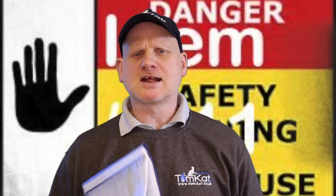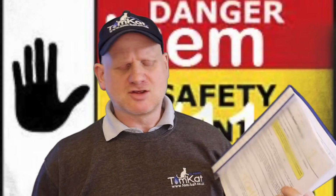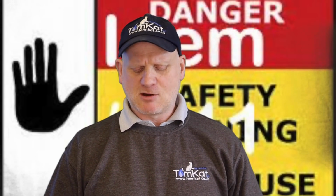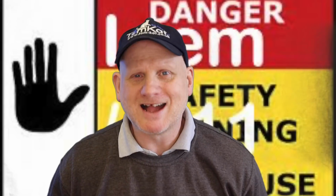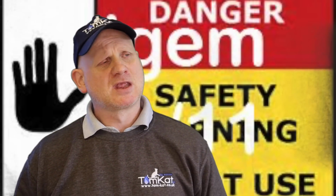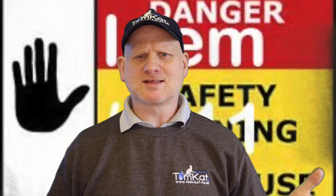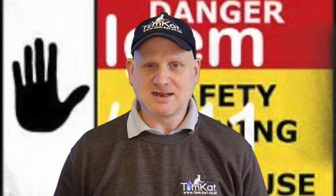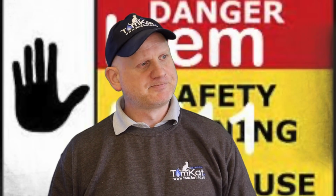Now, let's start part 2 off with classifications of flues according to our unsafe situations procedure IGEM G11. Now, what makes a flue ID? That is the question. So basically, it's quite simple. If a flue is terminated inside a building, it's immediately dangerous because it's putting products of combustion into that room.